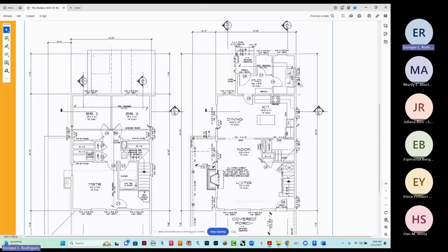Let's go back to this plan and let's see what we've got. Well, they got a width for the mudroom, which is 9'6", but I do not have a dimension here. So this might be something that is based on experience, but usually with your washer and dryer, you want a little bit more width. By the way, if this is a bathroom right in here, you don't want anything less than 5 foot interior width at this point.